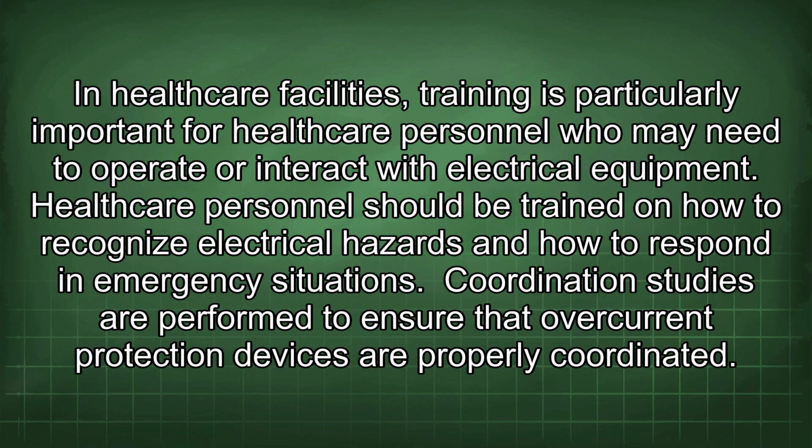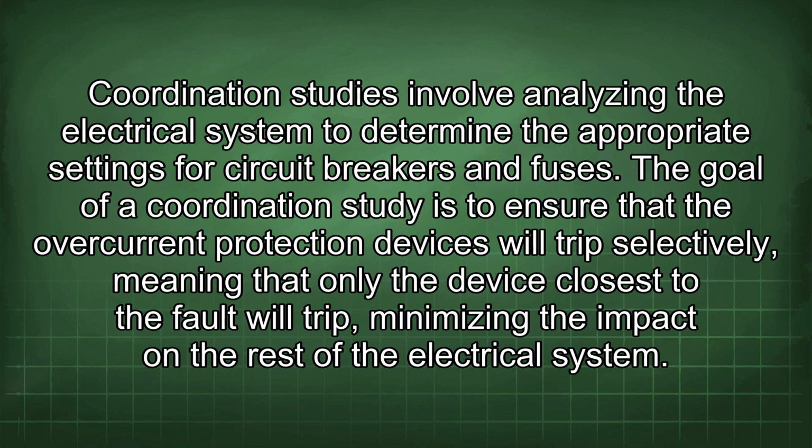In healthcare facilities, training is particularly important for healthcare personnel who may need to operate or interact with electrical equipment. Healthcare personnel should be trained on how to recognize electrical hazards and how to respond in emergency situations. Coordination studies are performed to ensure that overcurrent protection devices are properly coordinated. Coordination studies involve analyzing the electrical system to determine the appropriate settings for circuit breakers and fuses.